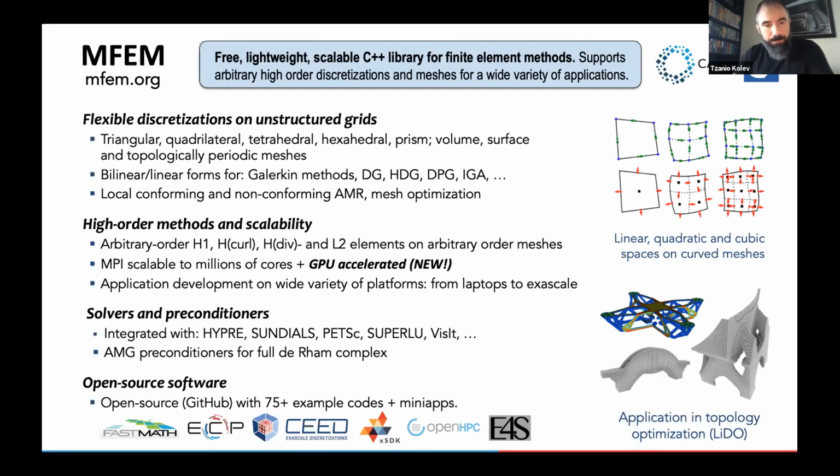One of the distinguishing characteristics of MFM is that it's very tightly integrated with Hypre and other solver libraries. For almost all of the discretizations that we provide, we have very scalable solvers. For example, we provide directly AMG accelerated preconditioning for all the spaces in the de Rham complex, including H-curl, for example, which is not trivial.